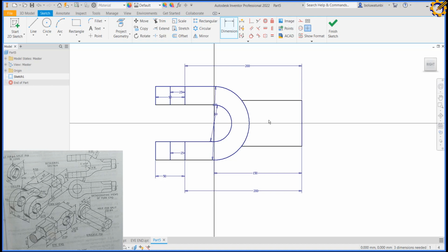Now towards the back here, I'm going to pick my thin line symbol, pick my line, stand right here, extend this all the way to the back right here, escape, up the thin line symbol. So I'm going to use my symmetric constraint. I pick top, bottom, and that thin line at the center. After doing that, the height of this area at the back, I'm going to make it height of 60. Yeah, this line, height of 60. Enter. So I have it in that order.